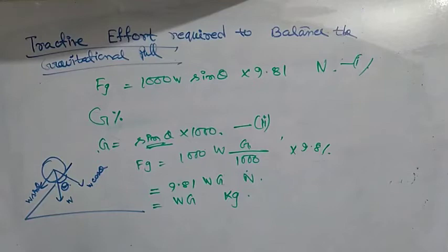On the other hand, if the ruling gradient happens to be in the middle of a rising gradient, the length of the gradient becomes very important in determining the temperature rise of the motor. Another factor which affects the overloading of the motor is the location of the signal with respect to the gradient, and if the stopping signal is at the foot of a rising gradient, speed pickup will be low and motors are likely to be overloaded.